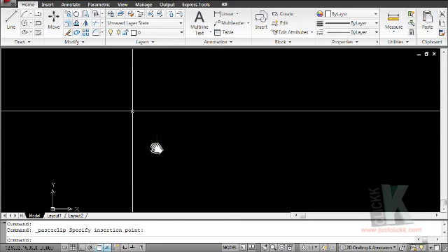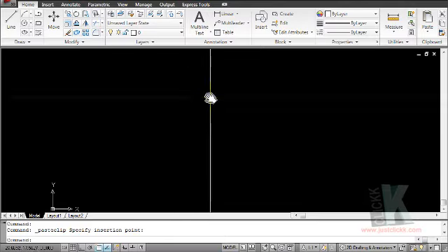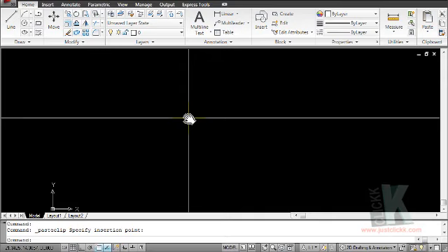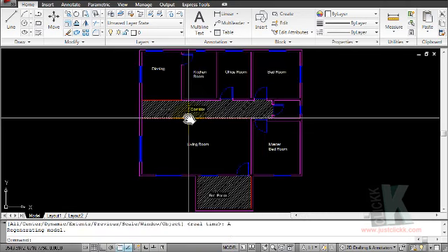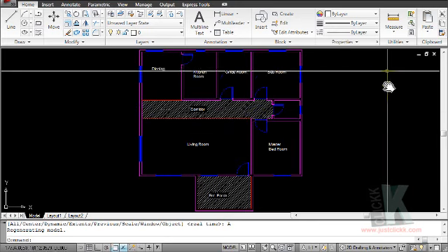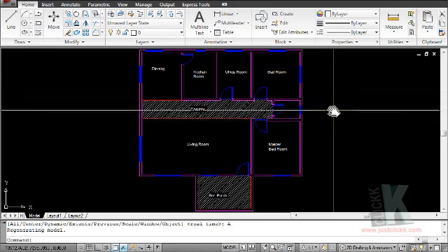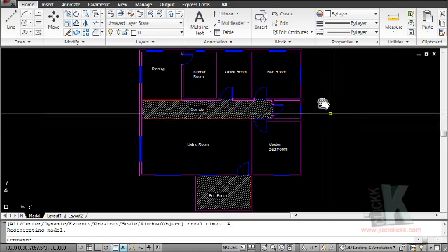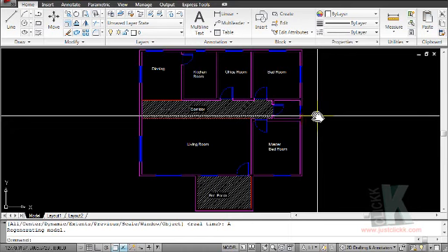And ordinarily, because the work environment has not been set up, you will have to zoom to the extent of the drawing. So let's type Z on our keyboard, press the enter key, and then type A, which means all, and press the enter key. And then it zooms all the drawings. If you have multiple drawings in this page, it will zoom all, but because we have just this one, you can see that it just pops up this particular drawing on your screen, telling us that this is the only thing available for the all screen range.